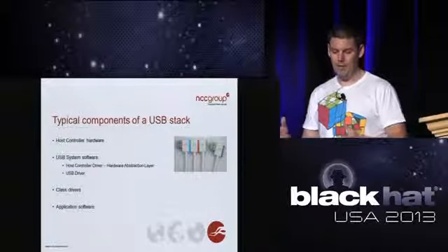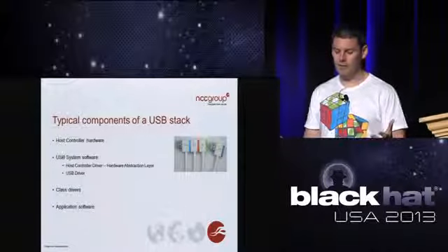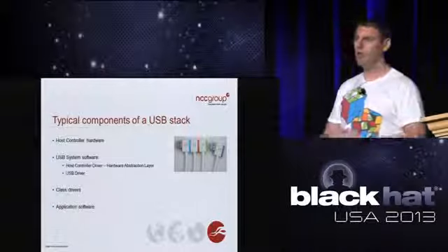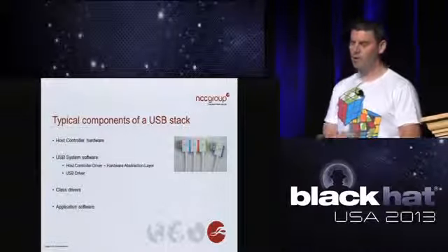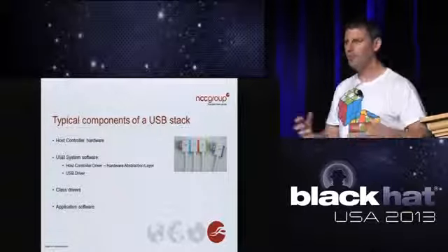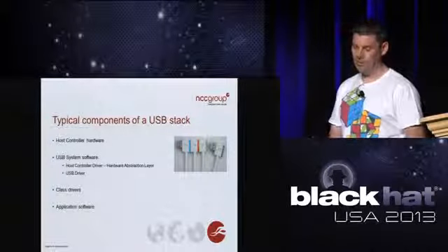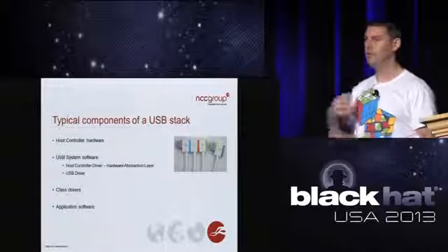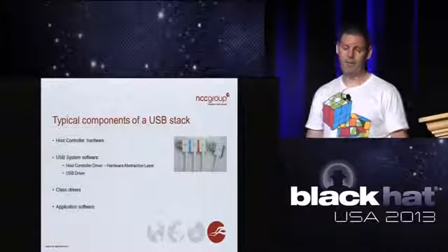Above the host controller, you'll have the host controller driver, which provides a hardware abstraction layer to the USB driver, which is the core component within the host that performs the enumeration that we just talked about and understands how to pass off information to the appropriate class drivers. Above that, you have the specific class drivers, for example, a mass storage driver or printer driver, that kind of thing. And then above there, the application software.